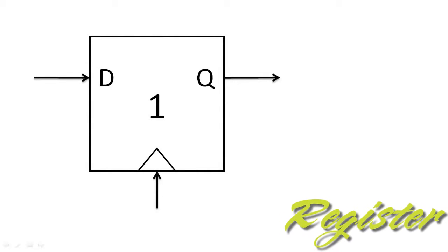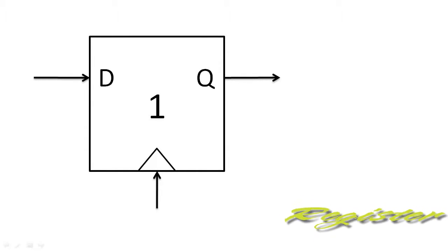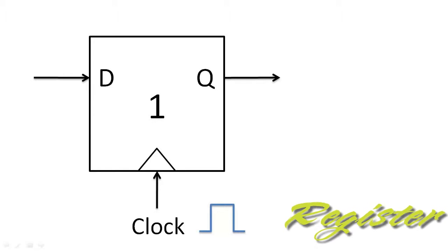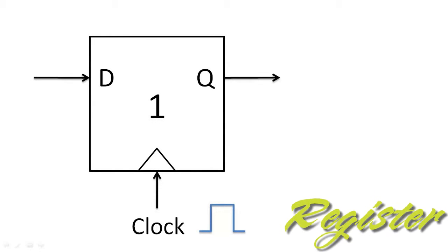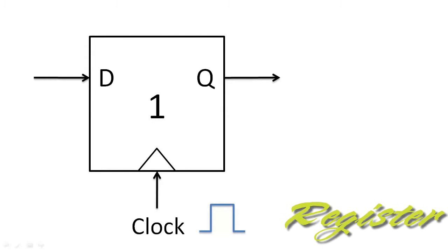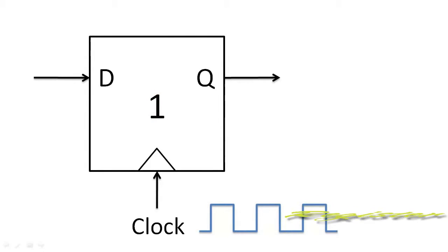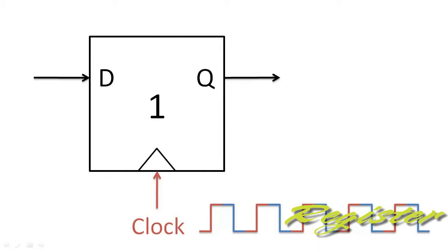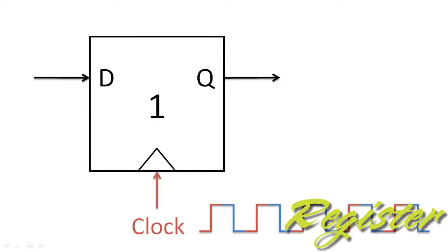Let's take a closer look at the structure of the individual flip-flops. Each flip-flop has 2 types of inputs. The first type is the clock input. The clock input is critical because we want all of our storage components to update at the same time. Consequently, each flip-flop is designed to update once per clock cycle. The flip-flops in this example are called positive edge or rising edge triggered flip-flops. So they will all update whenever the clock signal rises from a low voltage to a high voltage. Certain components that are controlled by the clock, like flip-flops and registers, are called synchronous components.